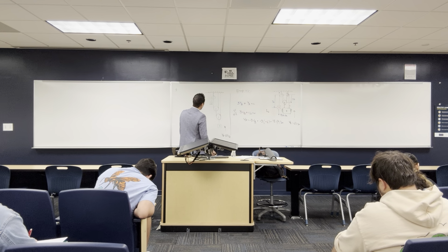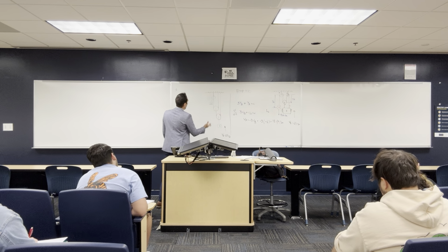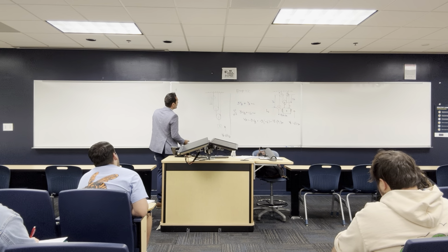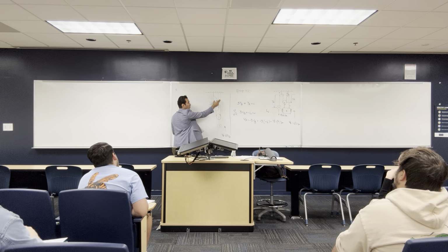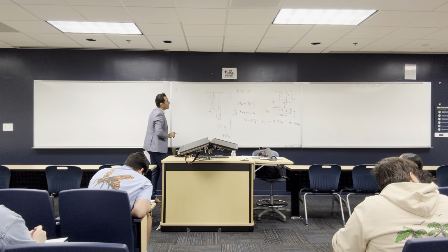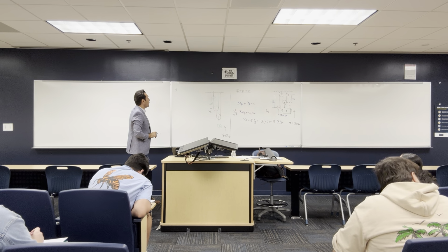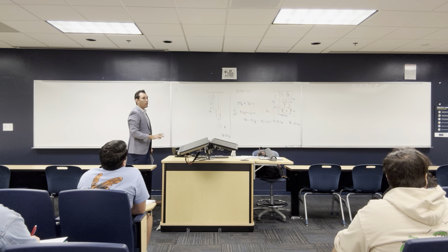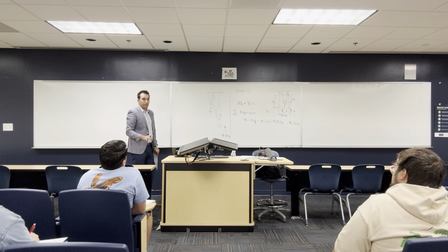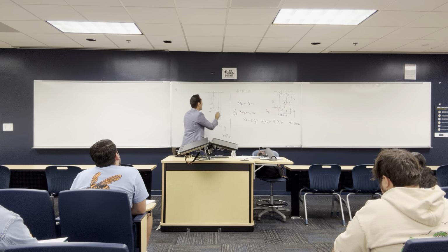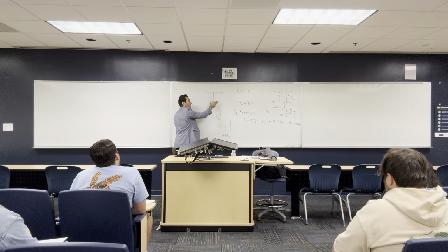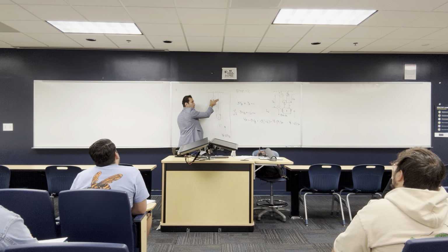Right, so let's look at this problem. So if VB is going up, how about VA? What is gonna happen to VA? Is it gonna go down or go up? This one is going up, that means all these cords are going up, so that means that A is going down. That's like intuition. All right, so you guys tell me, how many equations do I have in this problem? Here I only had one equation because it's only one cord that is constant. Now I have two equations because I have this one and this one. This cord is constant and this cord is constant, okay?